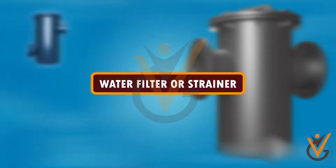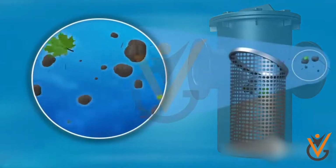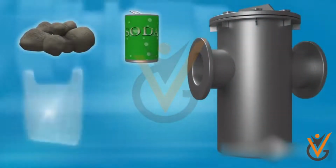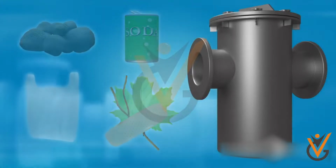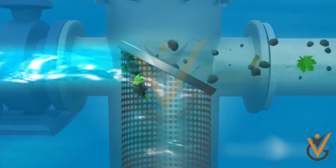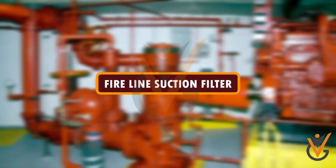Water filter or strainer. On board ship, seawater and fresh water systems are equipped with line filters to trap the system's strong impurities. The various water filter applications are: sea chest strainer. The sea chest is an enclosure that is attached to the inside of the underwater shell of the vessel and opens to the sea. It is fitted with a strainer that helps ensure that the flow of water in the line is maintained.